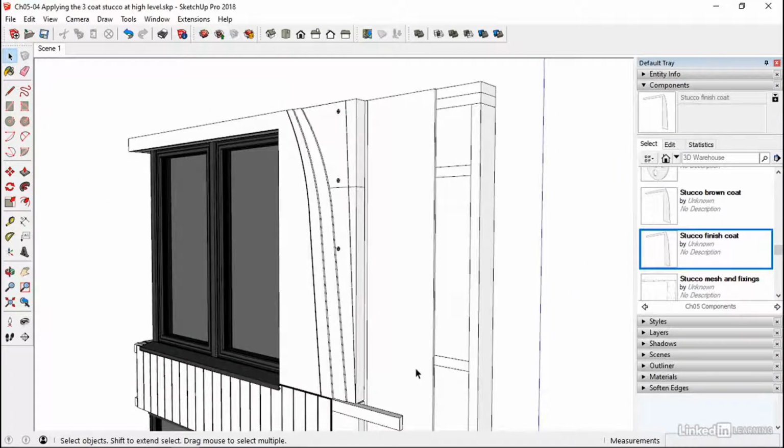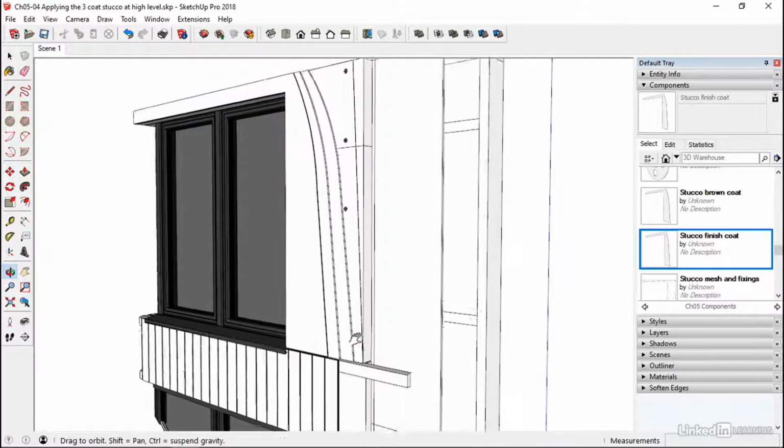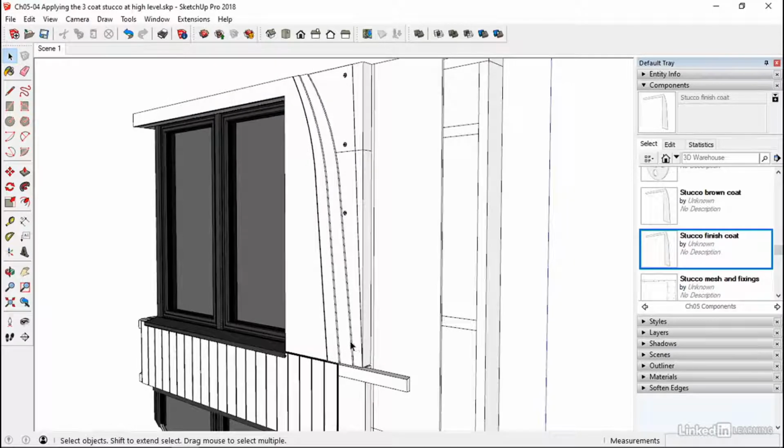And there you go. A few flashings to put in. The flashings are the things that sort of help identify the difference between the materials and make sure that we've got nice sharp edges, and also allows us to shed any water away from the facade where it is required. Okay, so we'll be doing some of those things next, and then moving on to the inside.